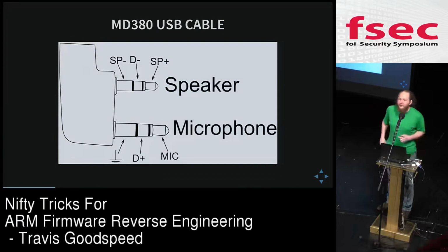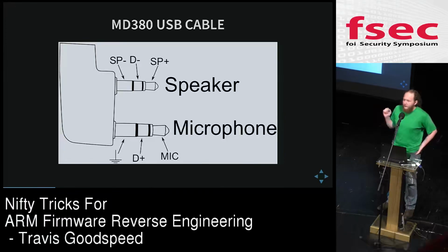One particularly nice feature about this radio is that it has an actual USB port. Most radios of this type instead have a low voltage serial port and require conversion electronics. Here, the CPU implements USB itself through one of 2 programs, either a bootloader application or the second layer application that's actually running the software that manages the radio that turns on the screen.